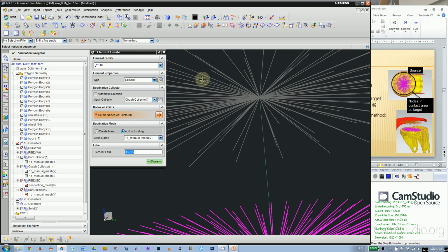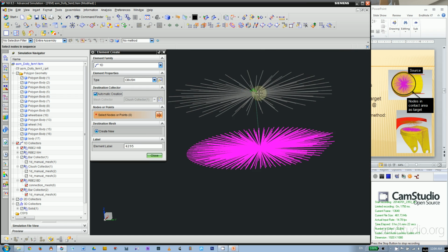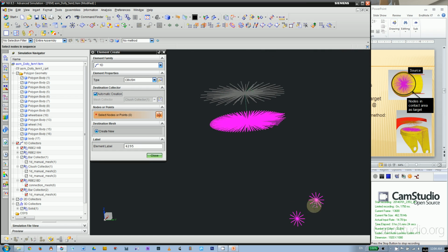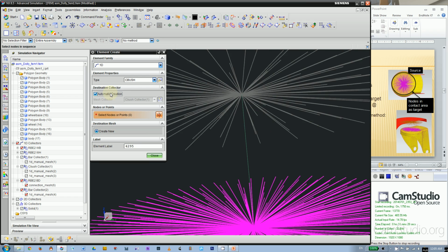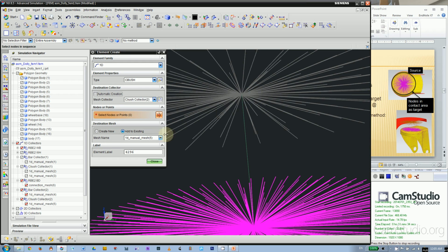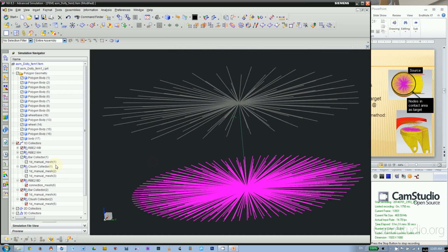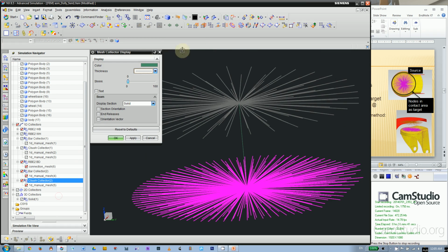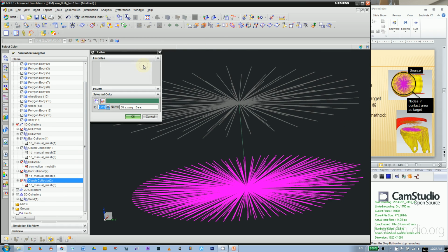Okay. So again, for this joints, we need a new collector because they're gonna rotate at the different axis as the wheel joints. So auto creation, select the 2 nodes for this at that spot, and then in this new collector, we're gonna change display, enable the tags.